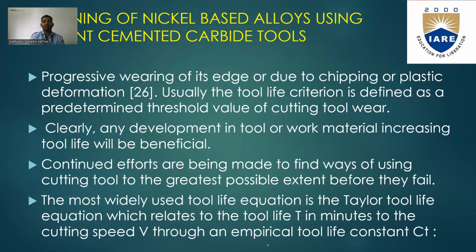Progressive wearing of the edges is due to chipping or plastic deformation. Usually, tool life is defined as the threshold value of cutting wear. Clearly, any development in tool or work material that increases tool life will be beneficial. Continued efforts are made to find ways of using cutting tools to the greatest possible extent before they fail. The most widely used tool life equation is the Taylor tool life equation, which relates the tool life T in minutes to the cutting speed through empirical constants.